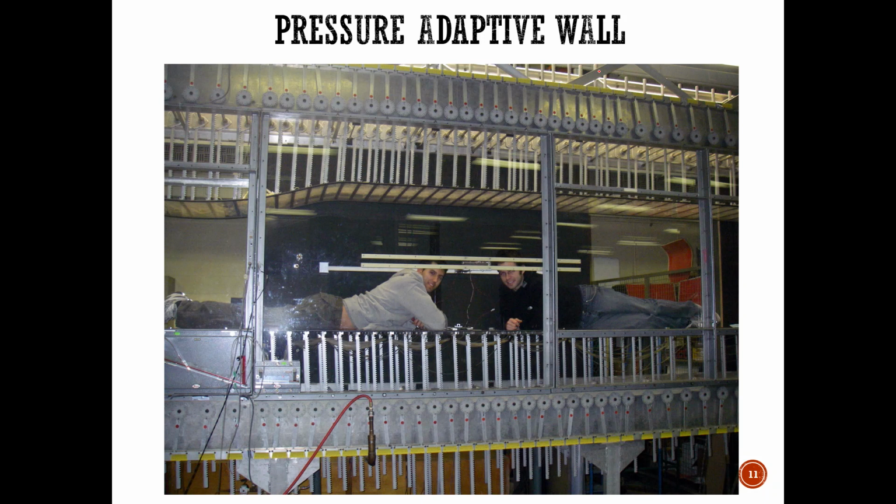Here is an example of a wind tunnel with a pressure adaptive wall, which means that you see the cross section of the tunnel surface on top. So using this adaptive wall mechanism, if they place a model something like this in here, say a car, right? Now, it poses a high enough blockage that the walls will interfere with the air going around the car, which interferes with the test measurements that are being taken. So what they do is they measure the pressure.